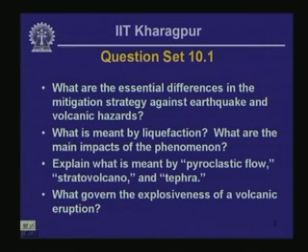The second question that I asked was, what is meant by liquefaction and what are the main impacts of the phenomenon? Now, liquefaction is primarily a phenomenon associated with elevation of pore water pressure within the matrix of relatively coarse-grained soils, which derive most of their strength from frictional interaction between the individual particles that compose the medium.